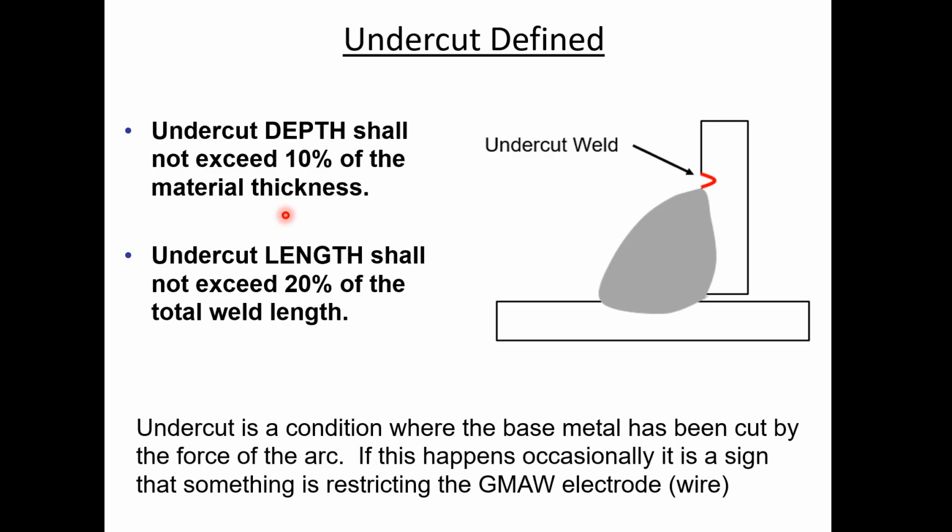So there's a couple of quick rules here. Now, these should be done, more of a note to engineering and quality, but these should be done in a border sample. You should have some type of a sample there for the people to see, to give them a visual gauge, if you will, about what's allowed and what's not allowed. I usually make up about, and if this is 20%, right, you could make a little bit of a visual gauge so they can see. It's 5 inches long, and there's 1 inch allowed for 20%. So there's some pretty simple ways to give people gauges to do this.